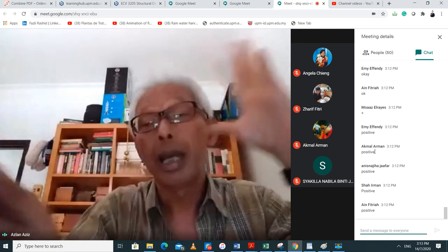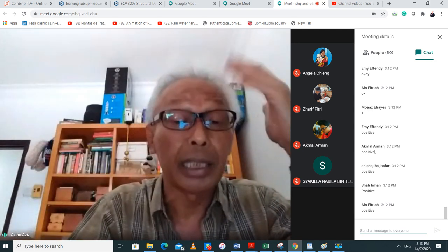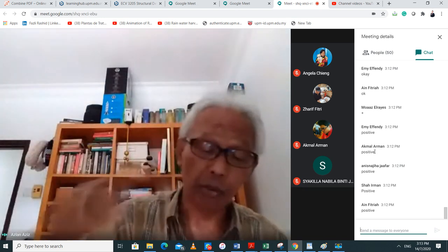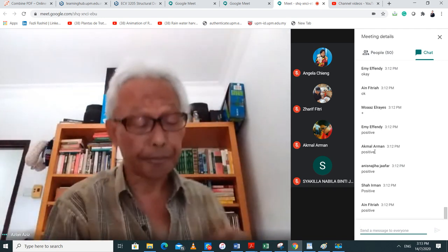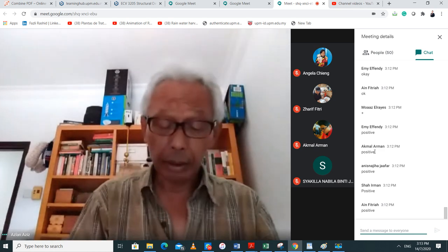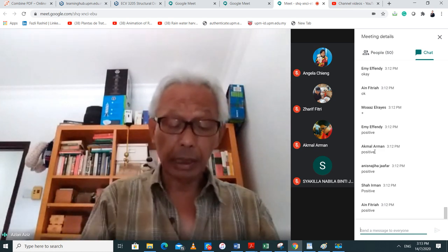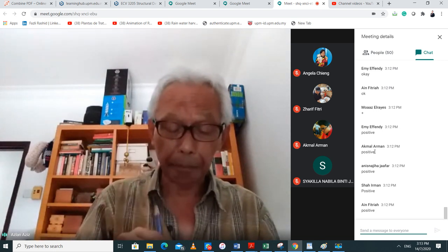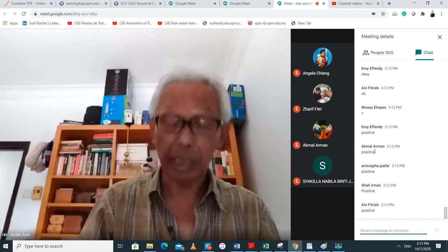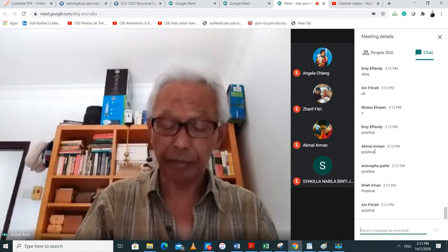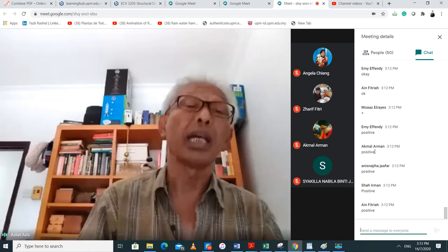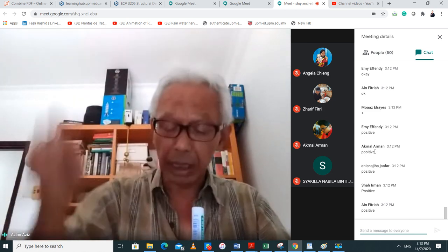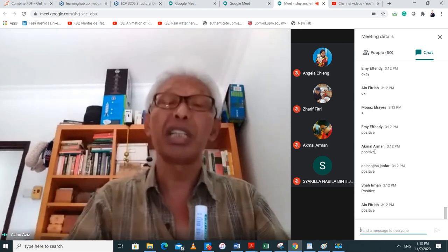So I need you to have this idea, so that you can see why they are doing all these calculations later on. The ultimate compressive load is the tip of the pile multiplied by the ultimate bearing capacity, plus the shaft friction multiplied by the skin friction. They said the load that must be applied is 650, so you multiply by the factor of safety, and the minimum you need is 1625 kilonewton.